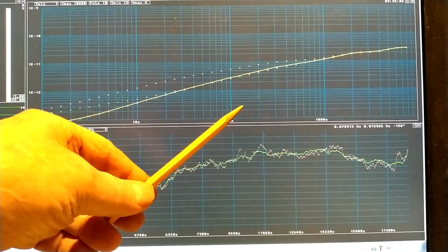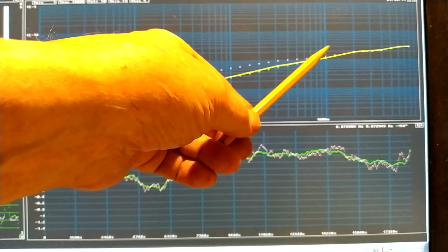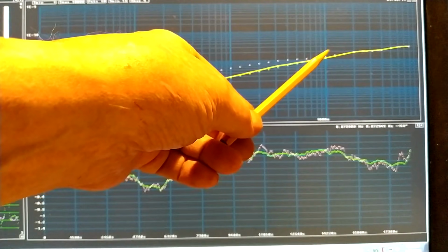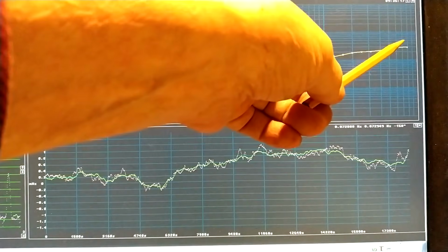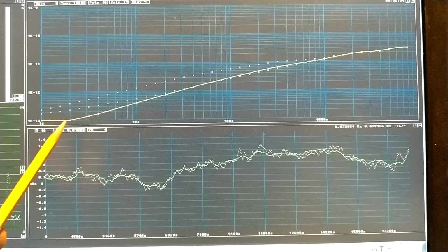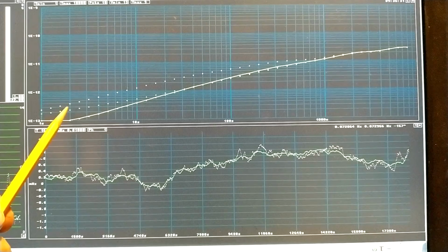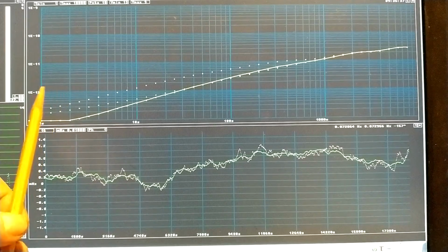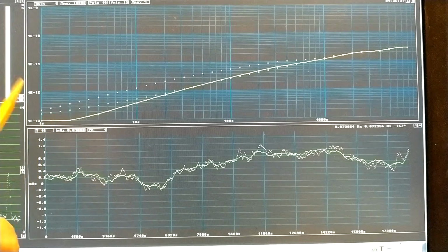And 1000 seconds is maybe long enough for the phase locking to make both my oscillators follow the same frequency. And at much longer times they are identical. But at short times, below 10 seconds, the oscillators are completely different. And I can see the correlated noise is much lower than what I have from one or the other oscillator. And that is, of course, seen very clearly in the phase noise graph of Linrad.